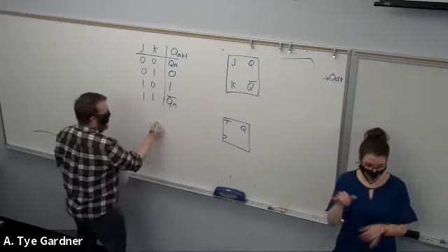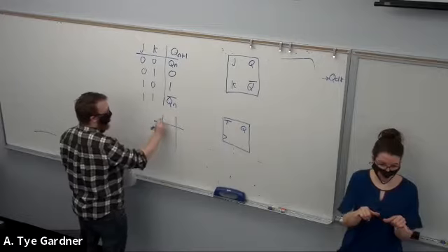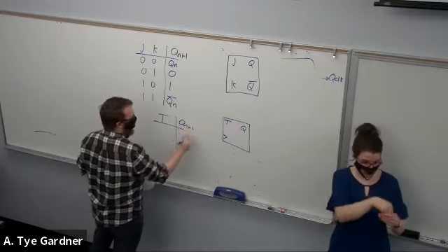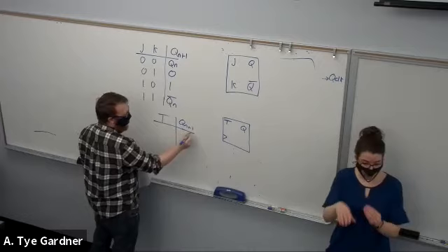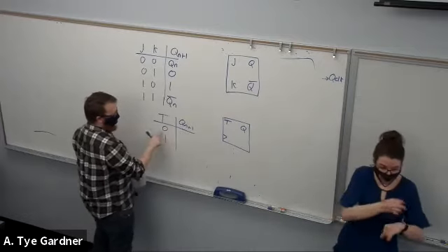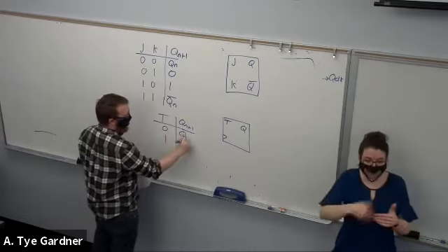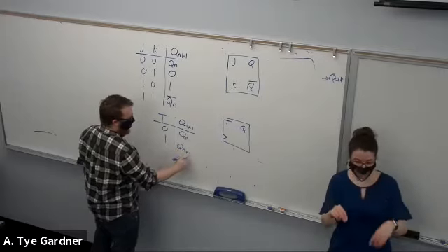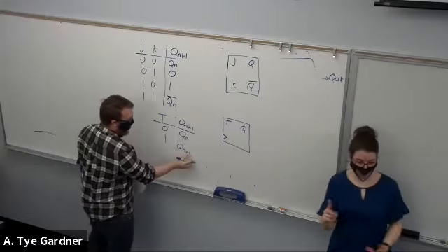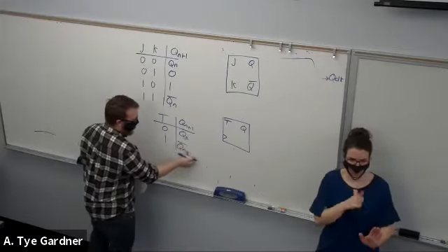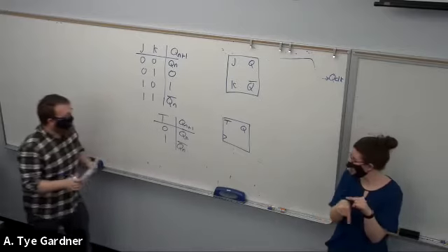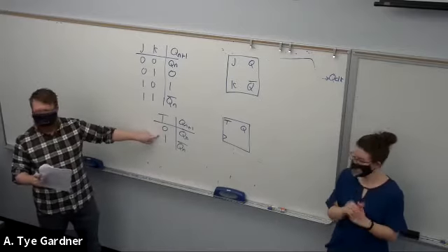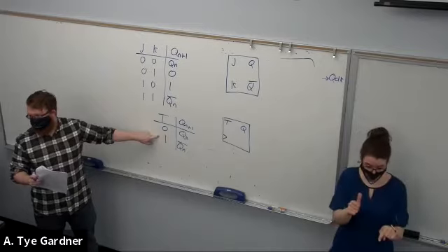So its truth table is really simple because it has one input, T. The Qn plus 1, meaning the next Q after the clock edge, is just, if T is 0, Qn, and if 1, it's Q bar. Oh, sorry, wait, sorry, Q bar. All right, so don't toggle, toggle. That's all the T flip-flop does.